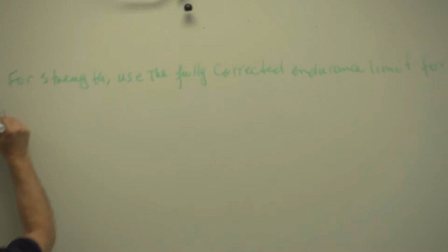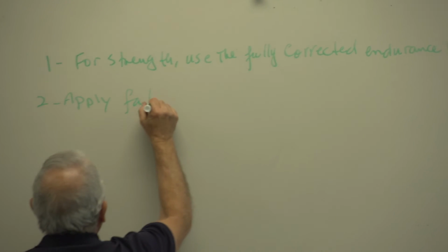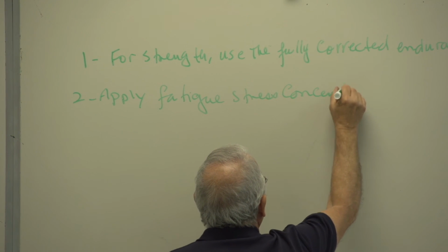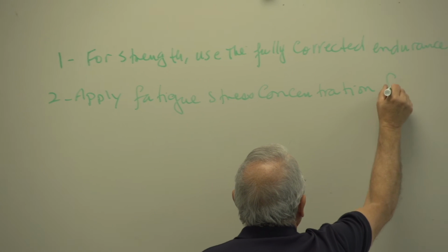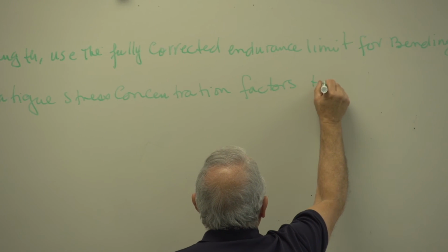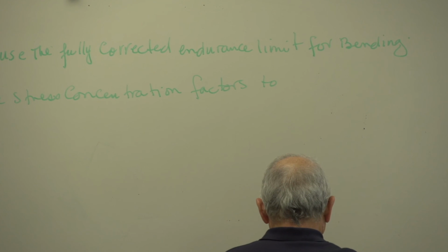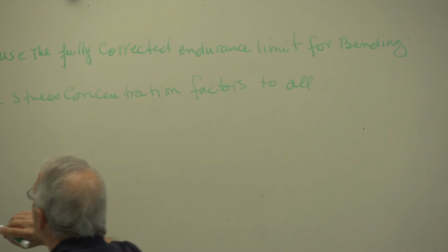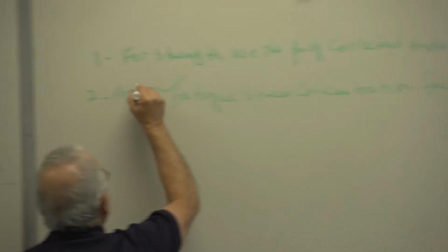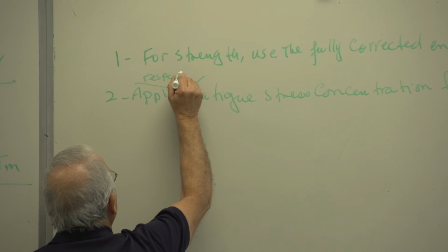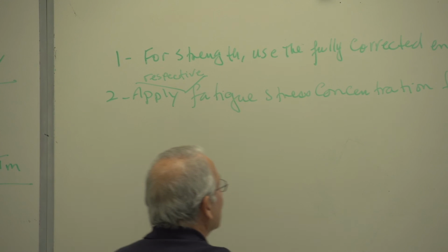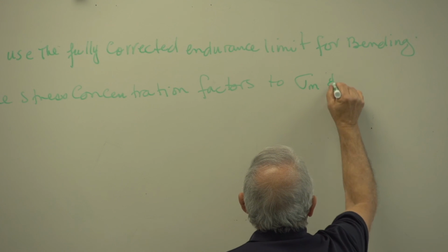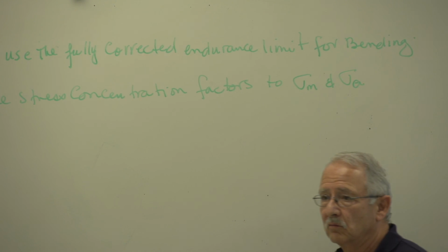2, apply fatigue stress concentration factors to, I should say apply respective fatigue stress concentration factors to sigma m and sigma a, just like what I did on the board in that example problem.